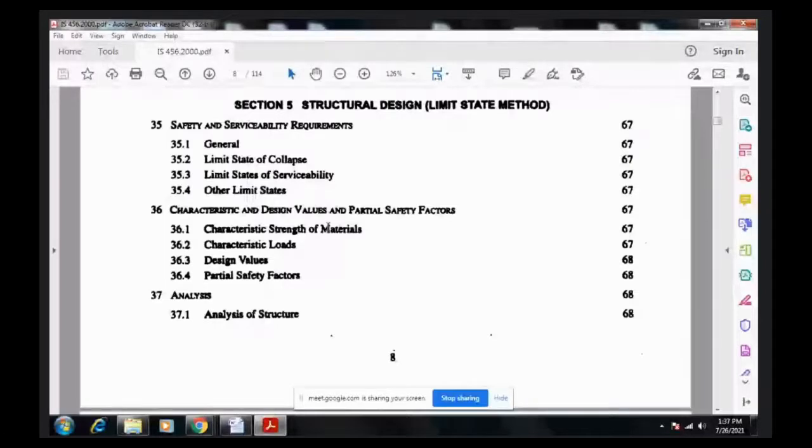But for other kinds of structures, suppose a building, due to wind load, there is some stress, again release. That is not like this. The level of fatigue, that kind of repeated loading and release of stress, is not like that. Here, we should try to use the strength of the material to the maximum extent. Of course, there will be some factor of safety because you are not sure what is happening at construction.